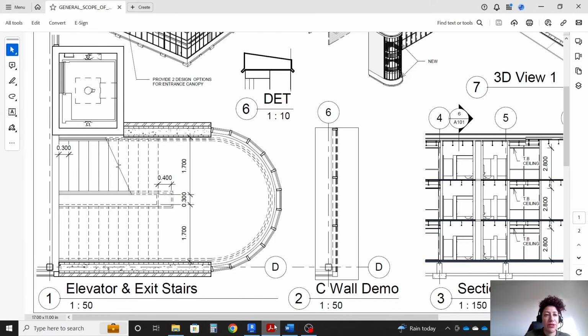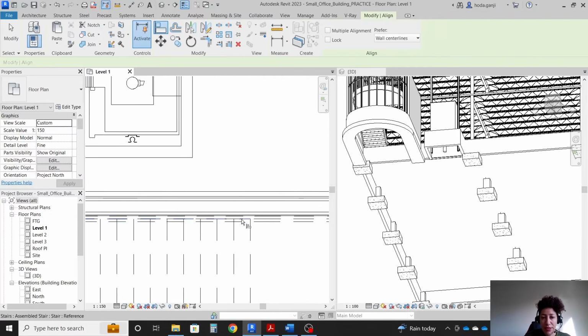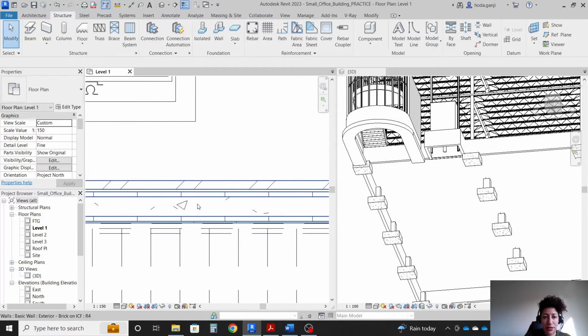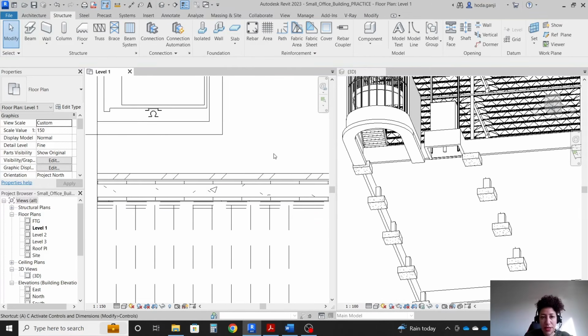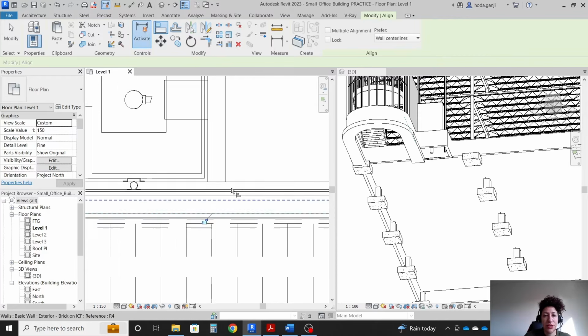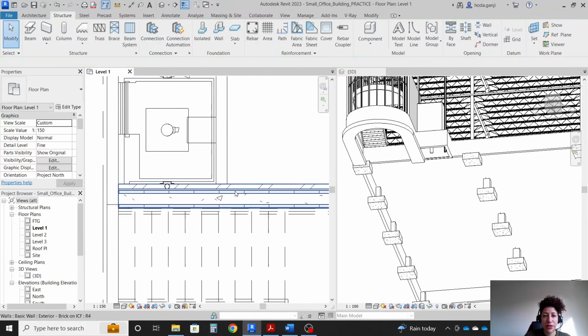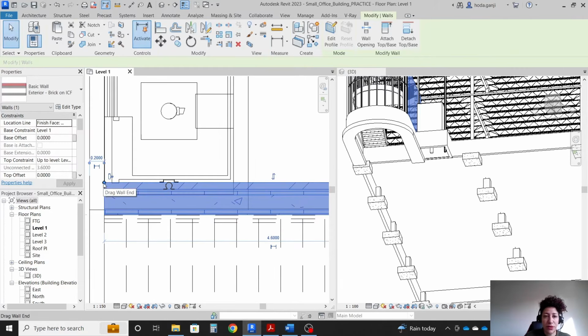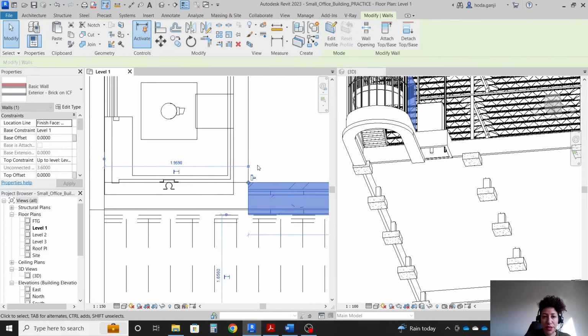And the other side of it should be in a way that the concrete part of the shaft matches with the concrete part of the wall. So that would make sense, right? The concrete is continuous. So that means this is the concrete part of the wall. I need to go with AL, hit tab, select the concrete edge, then click here. So the concrete matches with the concrete. Then I can move this wall all the way over here.